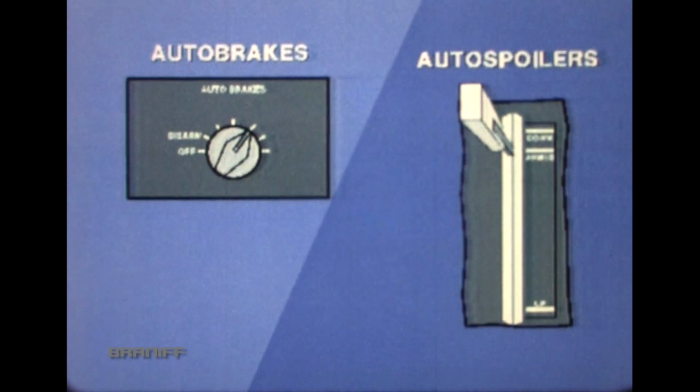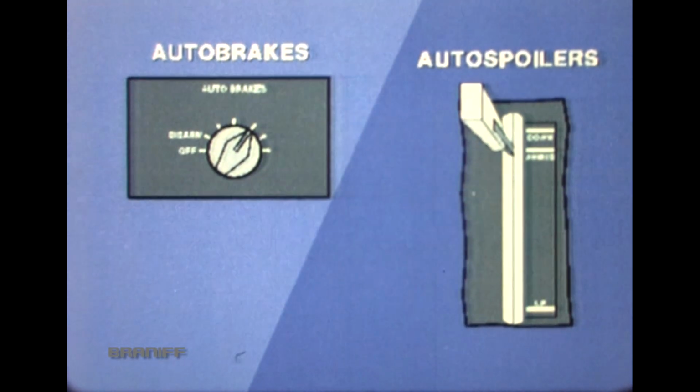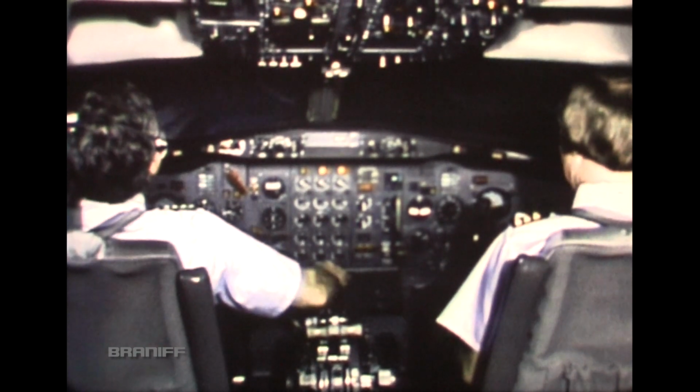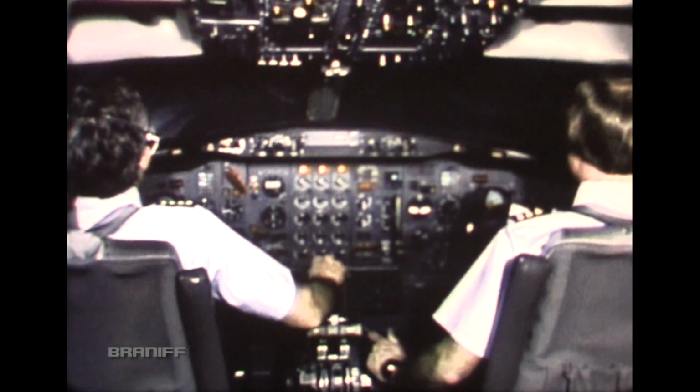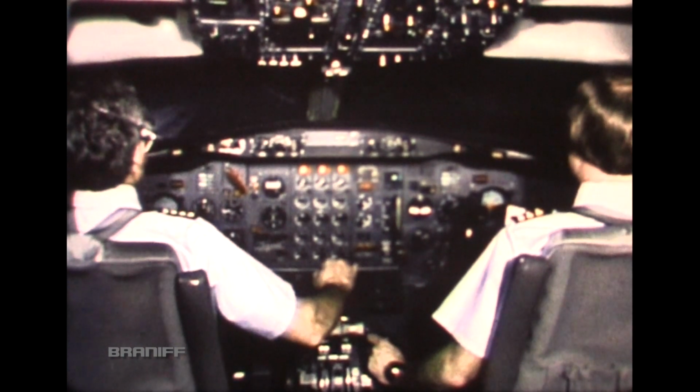Landing on ice or snow-covered runways deserves special consideration. All available means of stopping the airplane should be employed. If available, arm the auto brake and auto spoiler systems before landing. Deploy the spoilers immediately after all main gear contact the runway. Lower the nose wheel and actuate symmetric reverse thrust. Do not hold the nose gear off the runway.